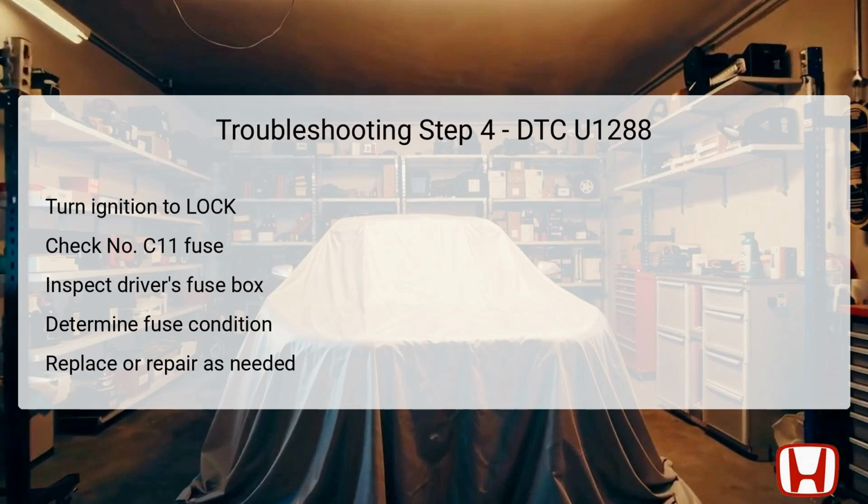After visually inspecting the fuse for any visible signs of damage, check if it is intact. If the fuse is functioning correctly, you will need to investigate for any opens or high resistance present in the circuit path. If the fuse is blown, replacing it is a straightforward solution. But if it blows again, this is indicative of a deeper issue, requiring you to check for potential shorts to ground within the circuit.